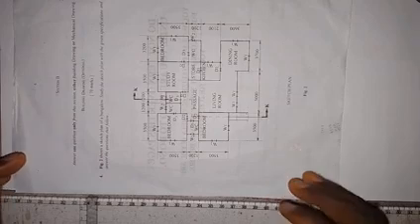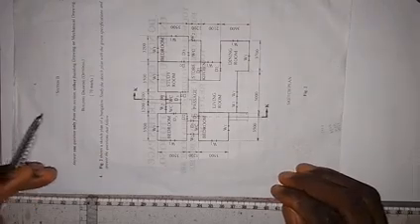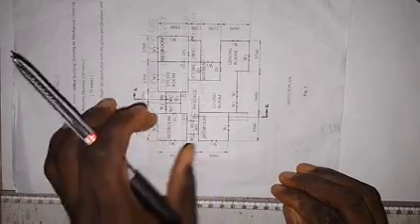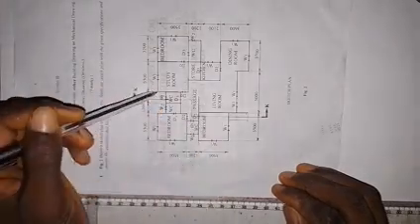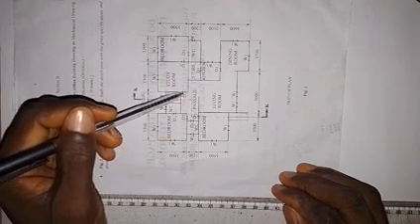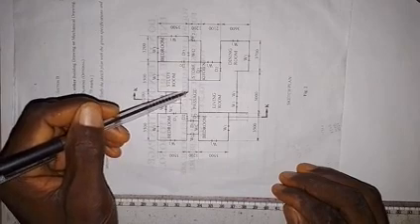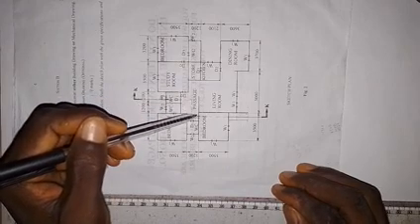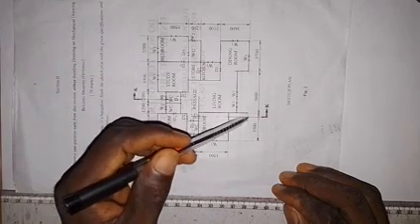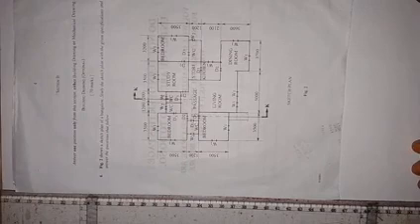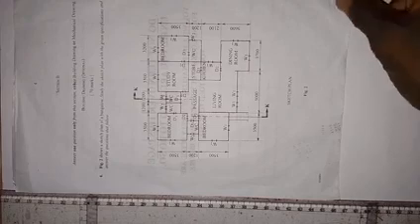Then we are also going to take note of what we can see around here by the time we remove this part. We are going to see the edge of this wall, as I said. We are going to see this door here, so we see this door, and then we see the edge of this wall. And then, coming here, we are going to see the edge of this wall. So those are things that we are going to take note of when we are producing the sectional view of this building. So let's start and see what we are going to get for this.